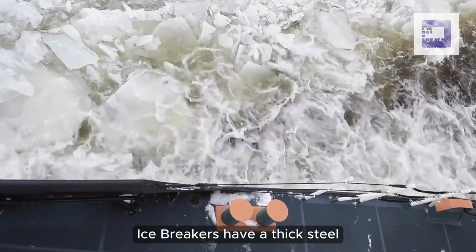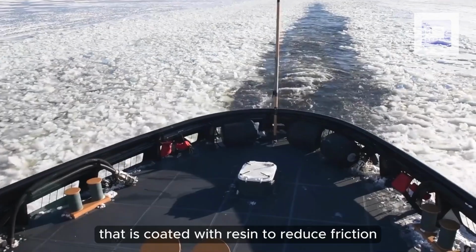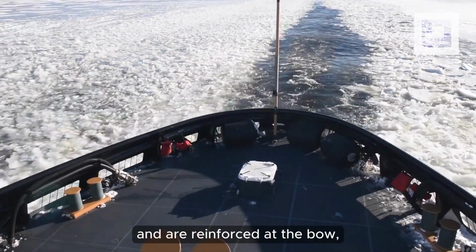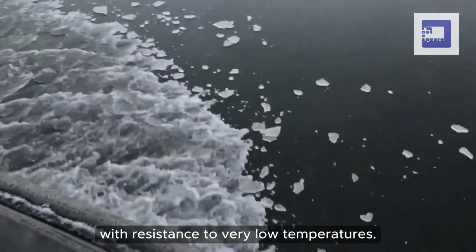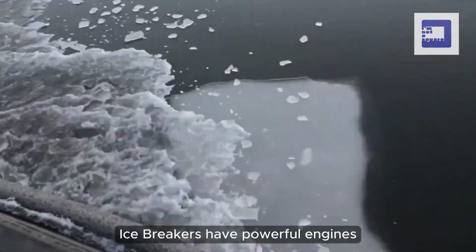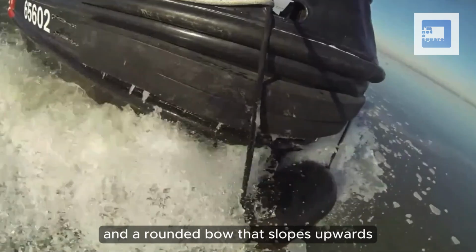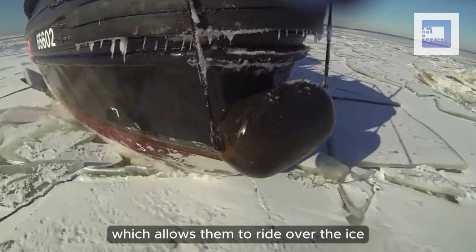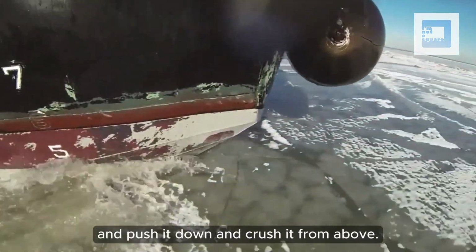Icebreakers have a thick steel double hull that is coated with resin to reduce friction and are reinforced at the bow, stern, and waterline with resistance to very low temperatures. Icebreakers have powerful engines and a rounded bow that slopes upwards, which allows them to ride over the ice and push it down and crush it from above.